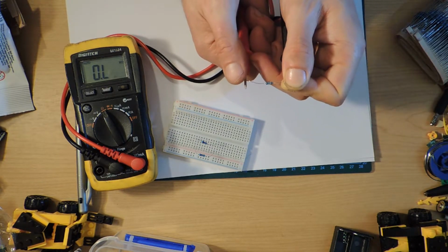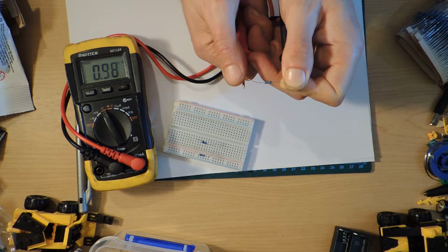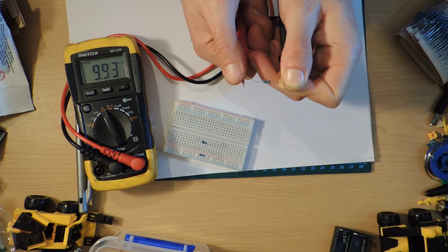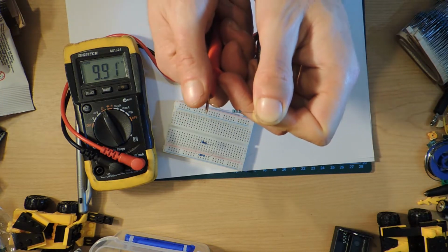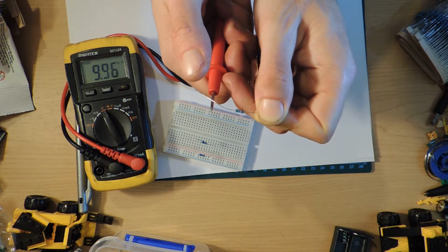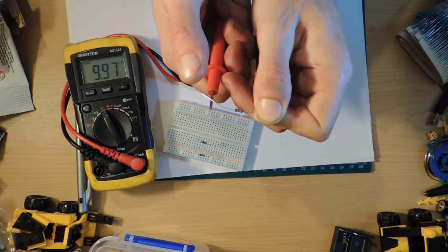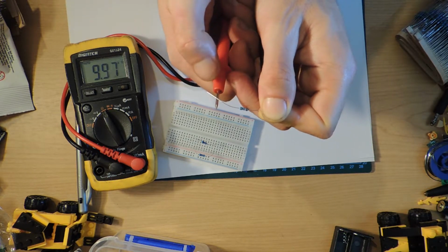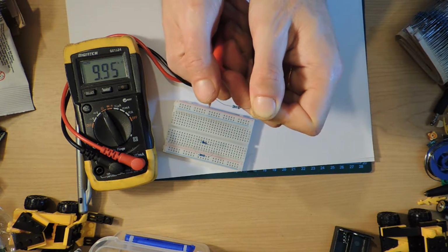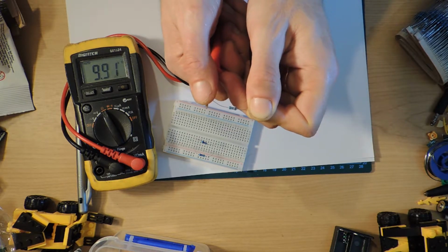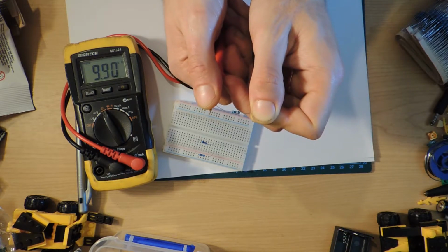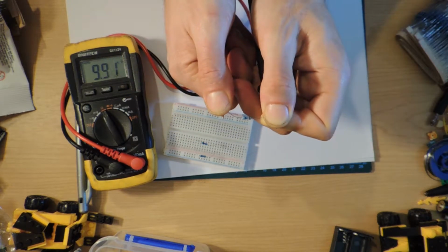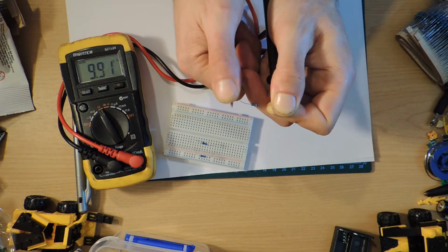Right, if I put this on here, it will say 9.93. In this case, it's actually also using me. So it's actually a parallel circuit when you hold it like this, because it's also going through my body. If I take my finger off it, the resistance goes up slightly, because when you hold it, you're making a parallel circuit with me as the other resistor. It's going through my body and coming out the other side, and that makes a difference that you can see on the display. So it's gone down a little bit, and if I take my finger off, it goes back up.